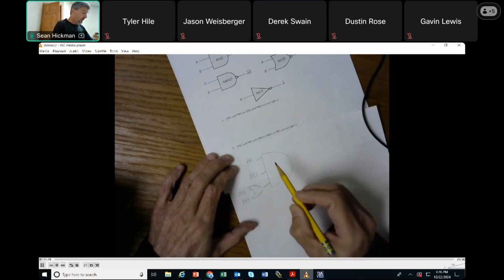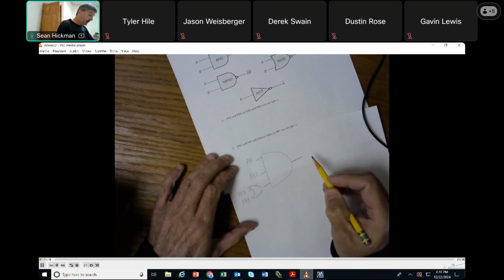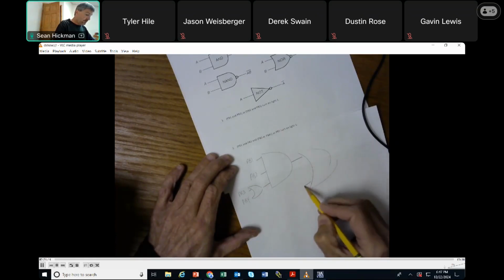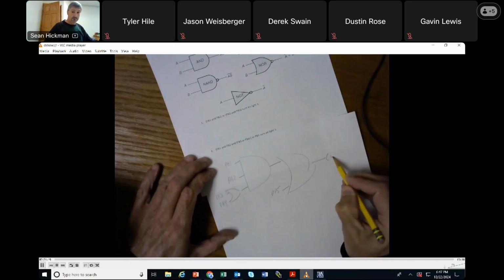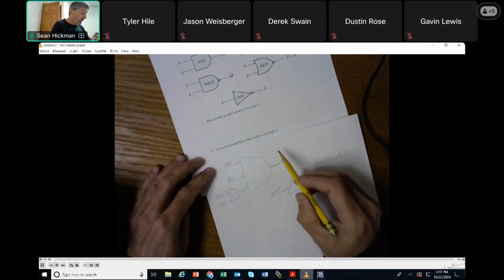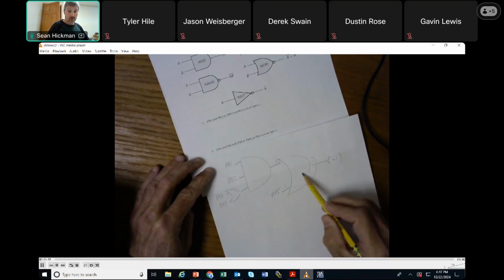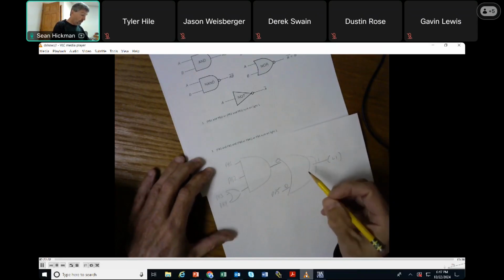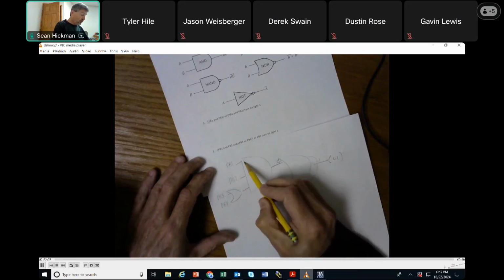So I got this and this and this, or PB5. PB5 gives me light 1. Okay, so it says OR. So if I had a 0 here and I push this button 1, I get a 1 there because it's an OR. If this was 0, I need a 1 up here. How am I gonna get a 1 here? Well, I got to push this, I got to push that, and I got to push one of these.